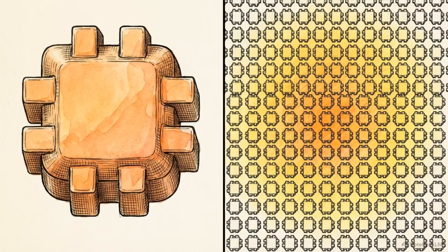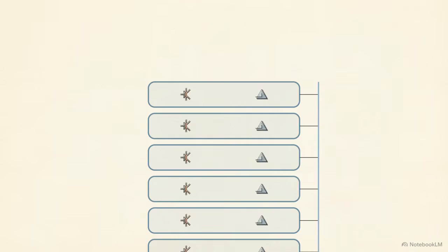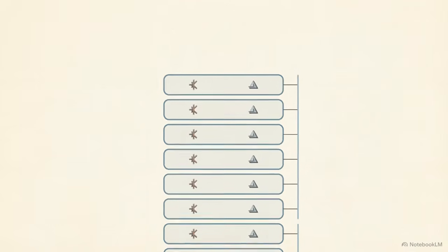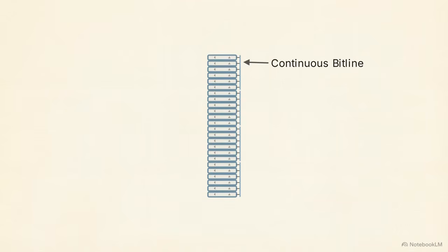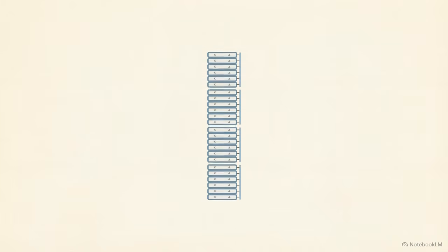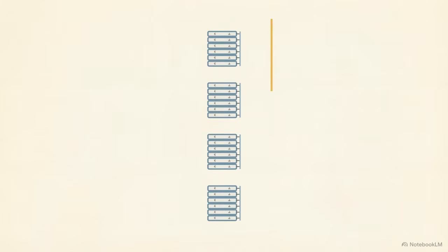Increasing the cell footprint with 8T or multi-port designs creates a compounding electrical problem when those cells are stacked into an array of millions. A massive, continuous bit line sharing thousands of access transistors carries heavy parasitic capacitance. This wire capacitance severely degrades read speeds and drives up dynamic power consumption across the system. The architectural solution to this is the hierarchical bit line.